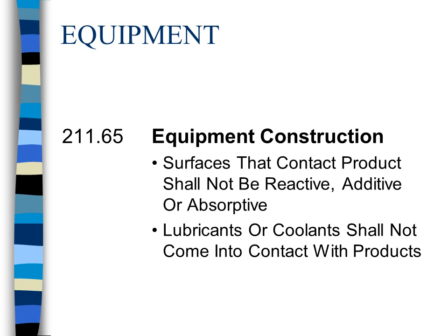An ignition source could be something as simple as static electricity, as simple as a heavy footstep on liquid oxygen. The compression of your footstep on liquid oxygen could cause a reaction. It could cause an explosion, or it could even cause a fire. That's why lubricants are not allowed around liquid or gaseous oxygen or any other medical gas product.